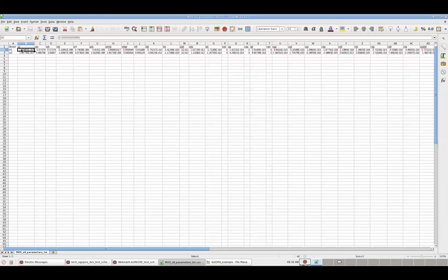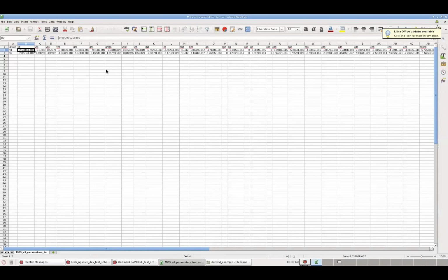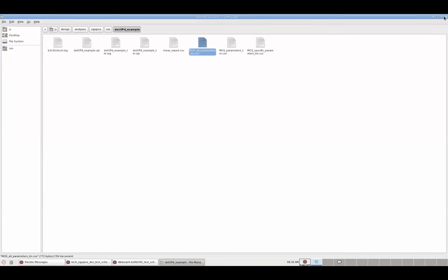all the device parameters, that is ID, VGS. So it's divided into the DC parameters, and then you have your capacitances towards the second half of the spreadsheet. And the first half contains parameters like the various voltages, transconductances, and the currents at every given node of that active device. So that's pretty much it.